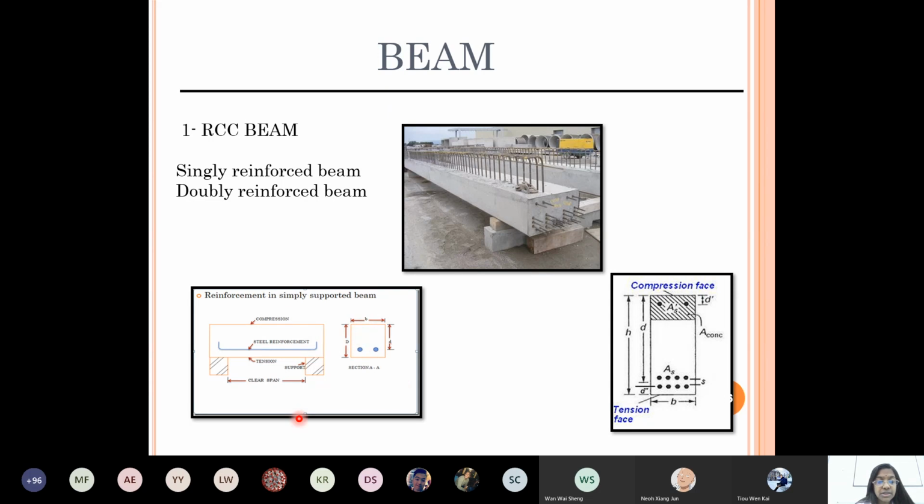And the cross section, the cut section of the member, if you cut the beam at this point and see the view, you can see the structure like this. This is the projected view of these rods, the reinforcement, and there are no rods here. That's why it's called singly reinforced. And then doubly reinforced will look like this. Then I'll show, oh, it's here.